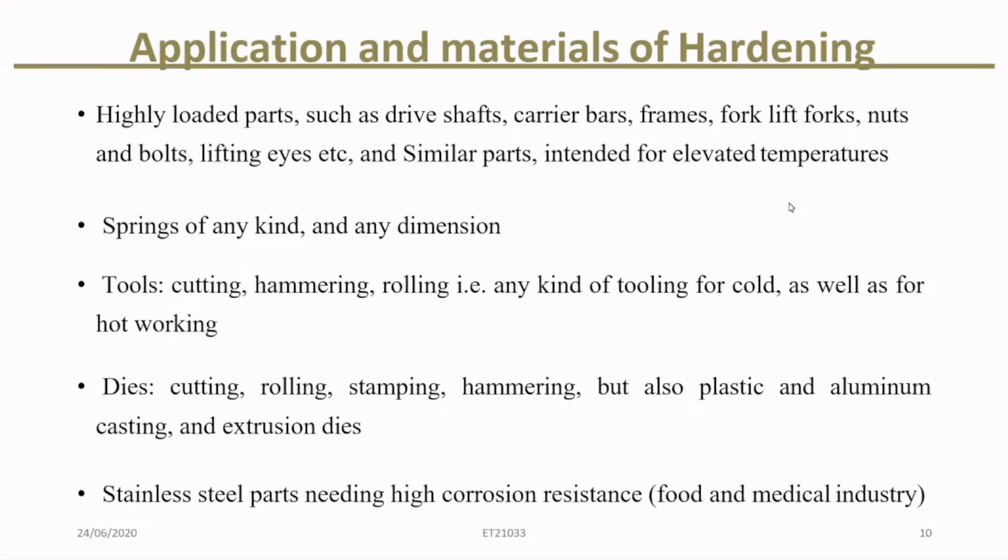And when we consider the materials, mainly carbon and alloy steel with enough hardenability to form martensite. For a hard surface with a tough core, we choose case hardening.